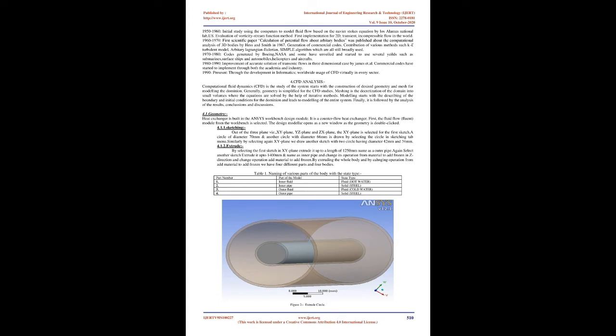Nagarani et al. used circular and elliptical annular fins. The heat transfer coefficient depends on the fin spacing, flow condition, and fluid properties. Fin efficiency was higher for elliptical fins than the circular fins.